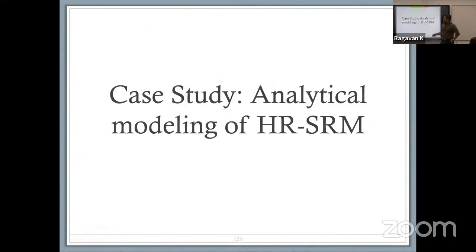So this actually is an analytical modeling approach that we specifically used to create the framework. Like I said, we have taken different perspectives at different times. We have tried to do co-simulation. We have done an auto-calibration model by identifying the inductance profile for a motor from the experimental setup. We have also gone into creating an analytical model that does MEC, magnetic equivalence circuit.